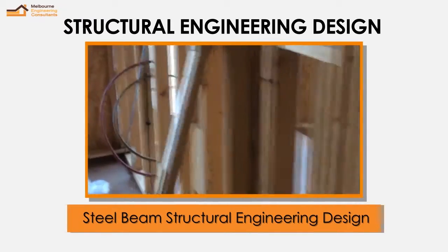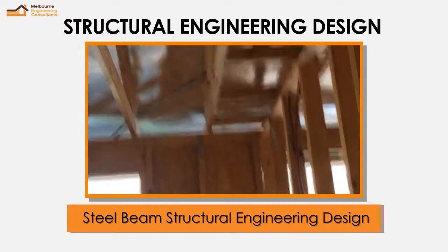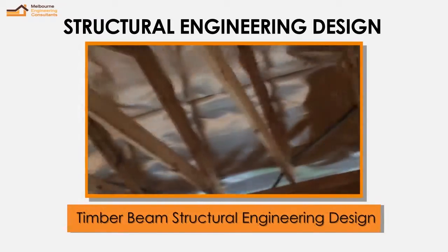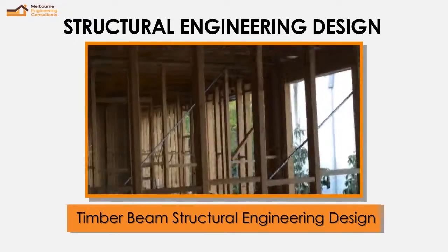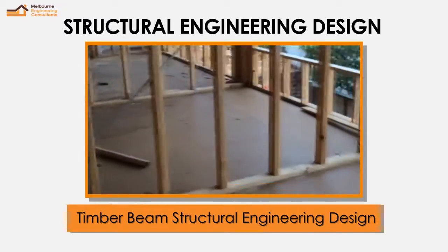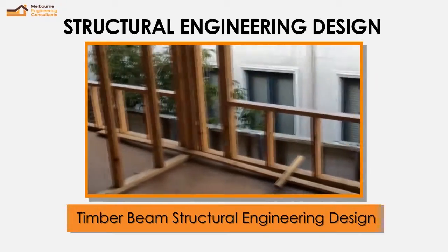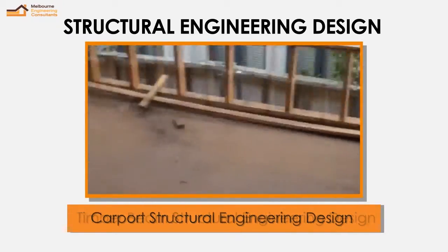Same thing here again. The lintel is a wide open lintel with the double strap on either end, and the roof trusses sitting on it with the hardwood bracing either end. Same thing, double D braces, as per Australian standards.